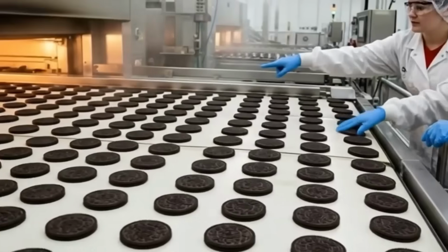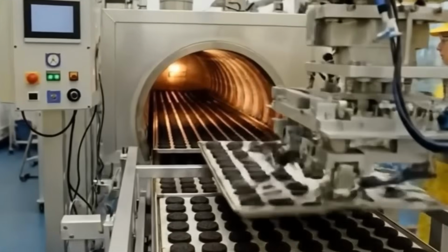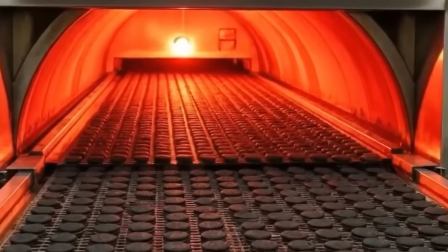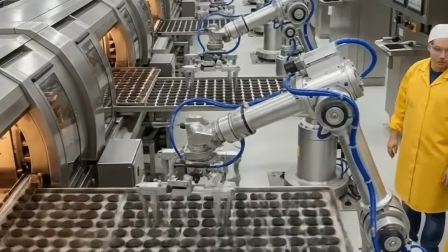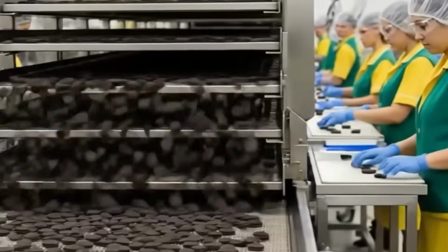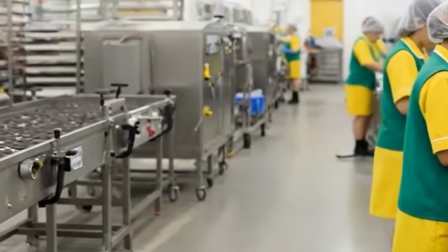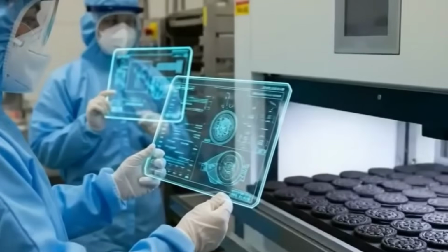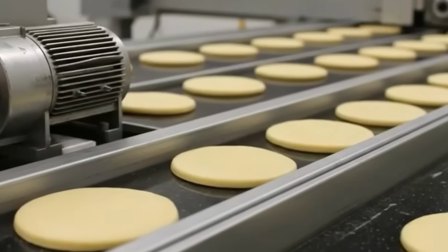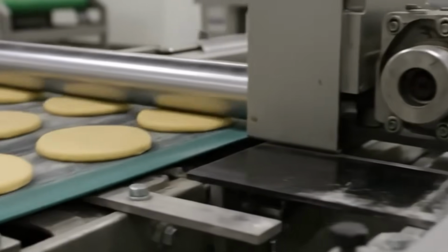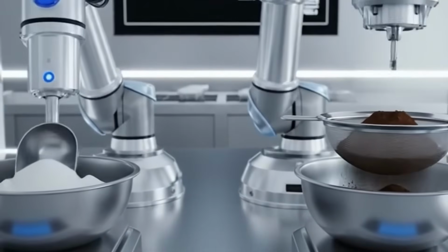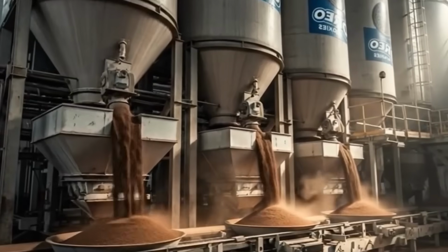Circular slitting blades mounted on adjustable shafts divide the wide wafer sheet into narrow, uniform ribbons matching the final roll width. Slitting accuracy is maintained using laser alignment sensors. Each ribbon is immediately guided into a spiral roll-forming station equipped with a rotating mandrel. A servo-controlled drum pulls the ribbon over the mandrel, while controlled tension and heat reactivation of the dough surface allows the strip to roll into a rigid, cylindrical shell.